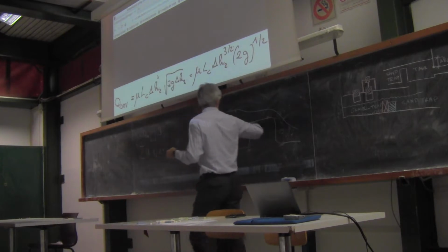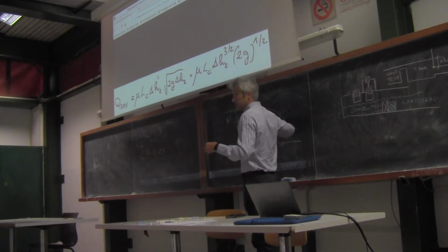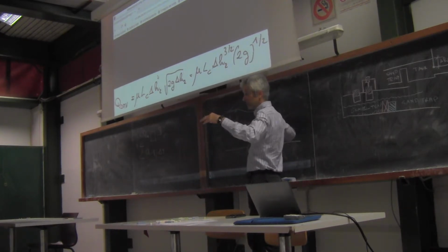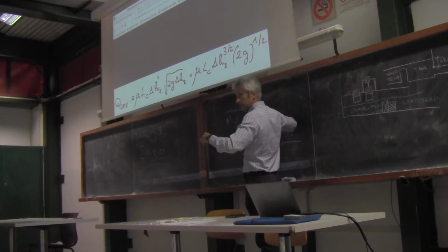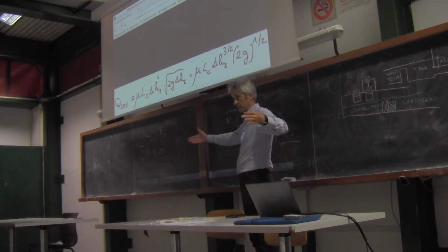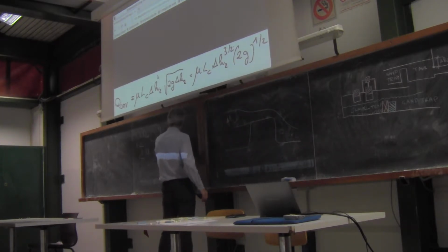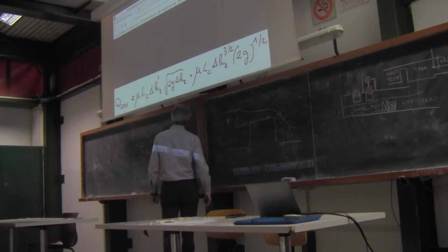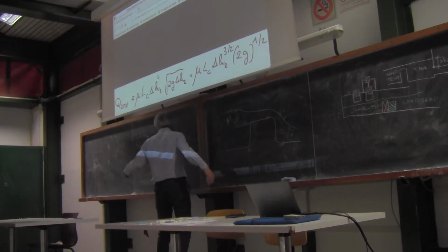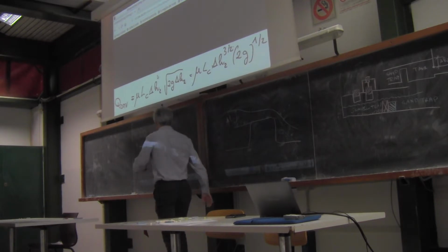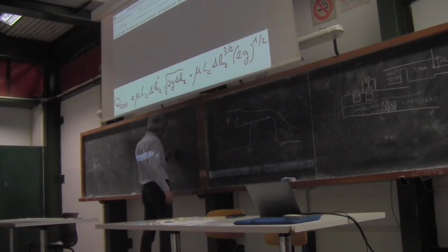This is a large crest. This is the crest of the weir. It's the top of the weir, and you see that it's long, meaning that it's large. For a large crest weir, μ is equal to 0.385. The large crest weir is also called Bélanger weir.